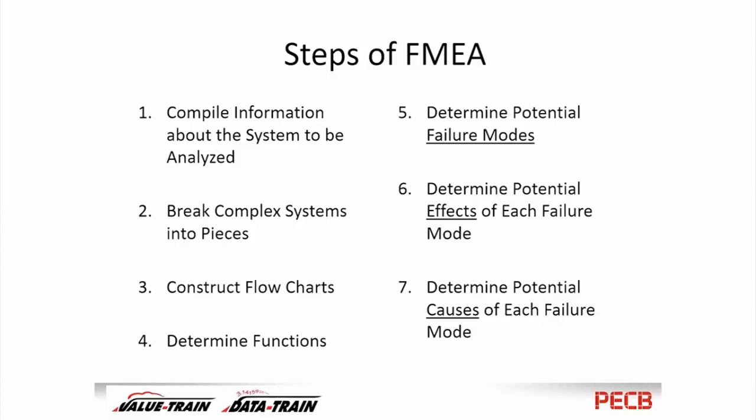And then once we have that, we'll take a look at if that failure happens, what effect will it have on my system or my customer? And as we're doing that, we can note what the causes of those failure modes are. We may not know, but if we do know, this is a good time to record it, because if we don't record the cause and we knew what it was, later on somebody's going to have to do this all over again to know what to fix.